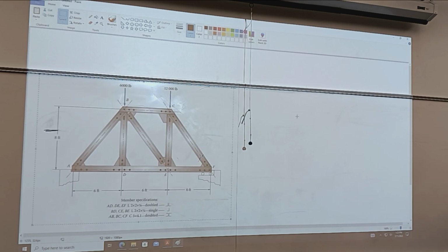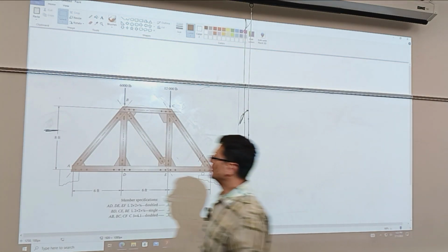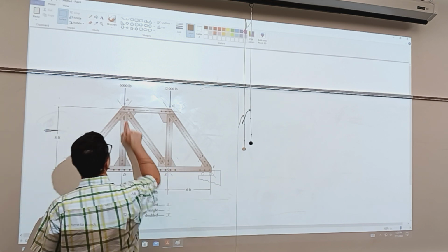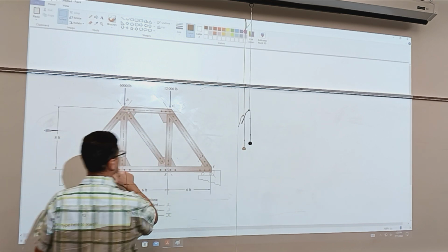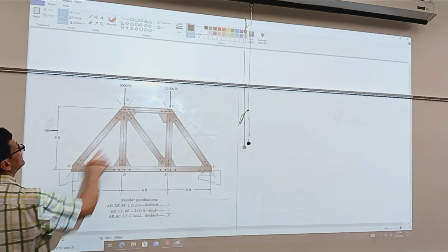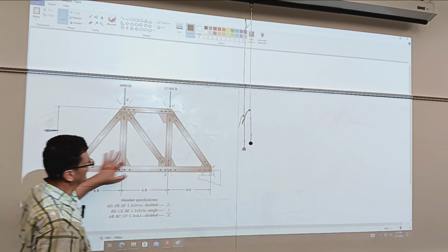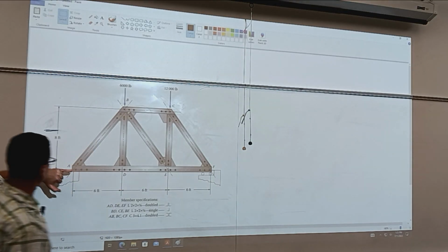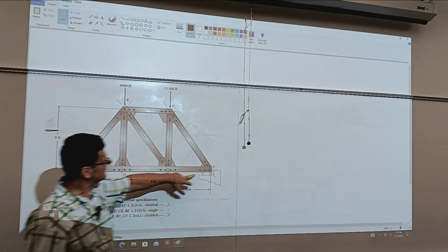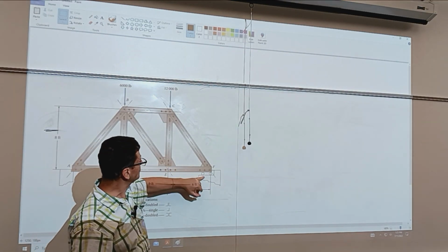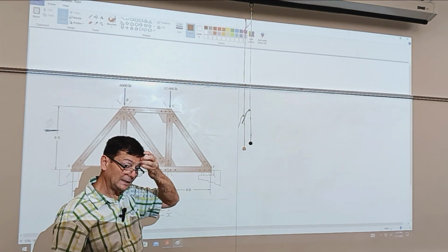All right, so have you seen this kind of problem in statics? We're assuming that these structural pieces are pin jointed, and loads are applied at the nodes. It's what we do, and we can solve it. Firstly, it has to be statically determined. So this is a pinned end, and this is a sliding point. You see them as a rule to account for any thermal expansions.